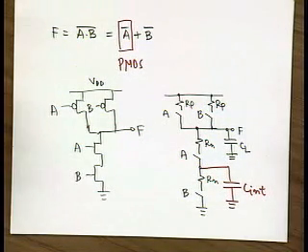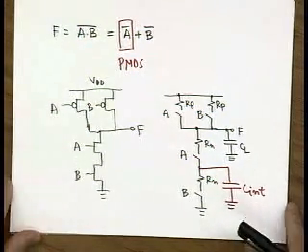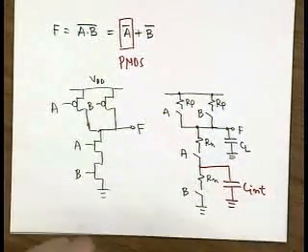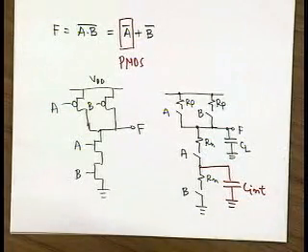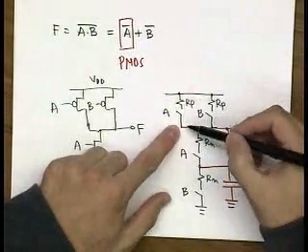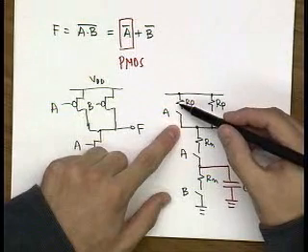Unlike an inverter, where you have a clearly defined topology for the pull-down and pull-up, in the case of a NAND gate this is no longer true, because you can have both your inputs switching from 1 to 0, or you can have only one input. So you have all of this data dependency. Let's see the case when only input A switches from 1 to 0.